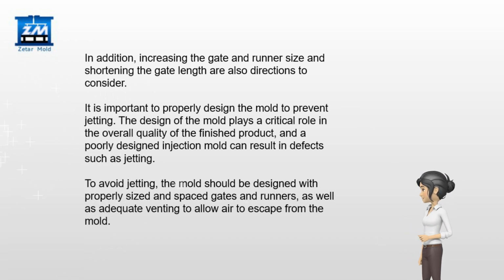The design of the mold plays a critical role in the overall quality of the finished product, and a poorly designed injection mold can result in defects such as jetting. To avoid jetting, the mold should be designed with properly sized and spaced gates and runners, as well as adequate venting to allow air to escape from the mold.